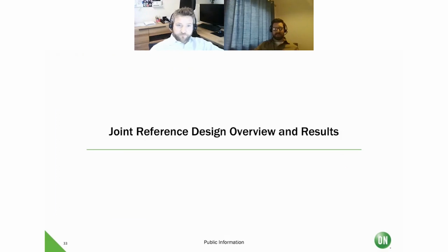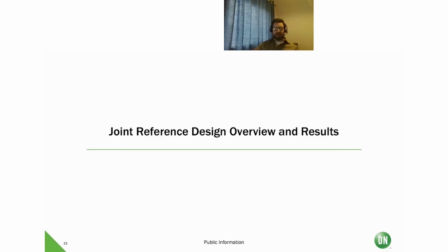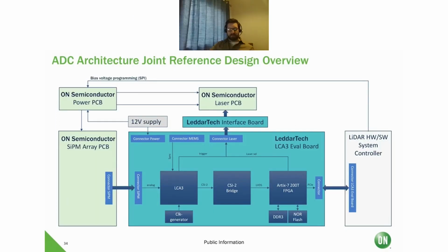Thanks, Rainer. So this is the block diagram of our combined reference design. It contains our onsemi SiPM array PCB. This PCB contains our 1x16 SiPM array, a lens mount, and a board-to-board connector that's compatible with the LCA3 eval board. We also have a power PCB, which provides the boost power supply for the SiPM array, and our laser PCB, which provides the illumination source.